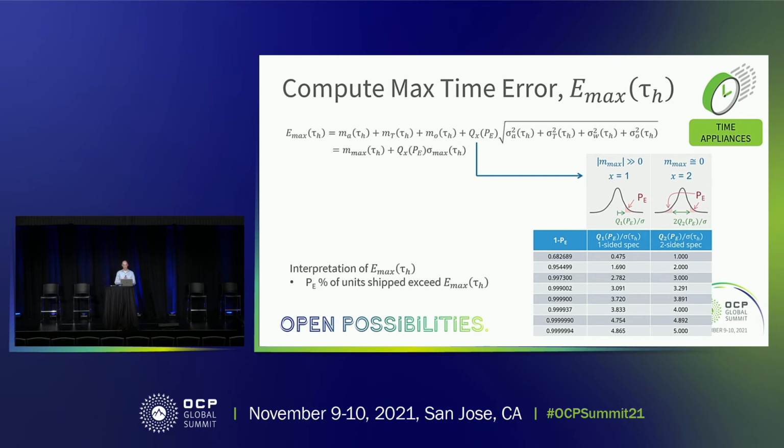And there's really 2 possibilities for this crest factor. If our final time error distribution is centered around 0, then the distribution that's leading to the maximum time error, which is shown in the rightmost column, could have errors generated either on the most positive side or the most negative side, and they're equally likely because it's a Gaussian distribution. And so in that case, you'd have Q sub x equal to Q sub 2 for a 2-sided distribution, and you would pick off your value here for your crest factor. So if you're interested in 6 nines statistics, then you would pick a 4.892 value for your value of Q sub x.